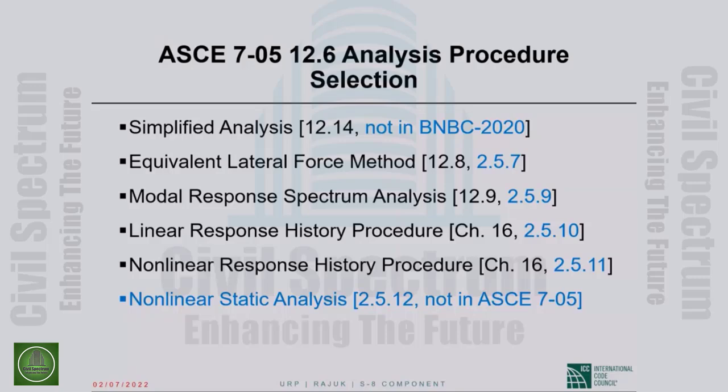Now, the inelastic behavior of these regions, the load displacement part, has to be modeled. And the success of nonlinear time history analysis, how good the results are, depends on our ability to properly model the load displacement behavior of these inelastic portions. Okay, so that's very briefly what we are talking about.